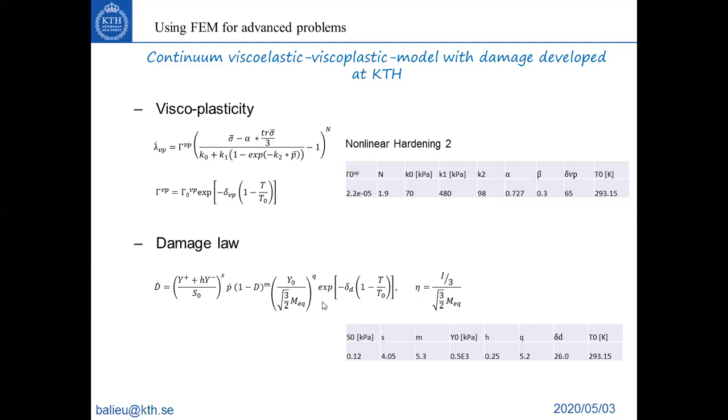And there is this damage law. If you look here, it is d dot. This represents the evolution of the damage. I don't want to explain anything here; I think it is out of the scope of this lecture. I just want you to note that this, of course, is temperature dependent with the same kind of dependency. It also depends on the stress level, and on whether you are in tensile or compression loading. I don't want to go too much into detail, but it is quite a very advanced material model.